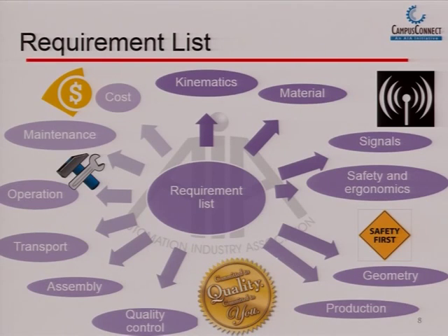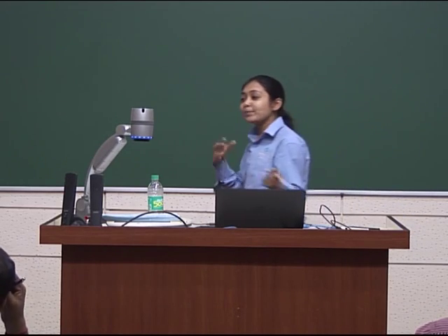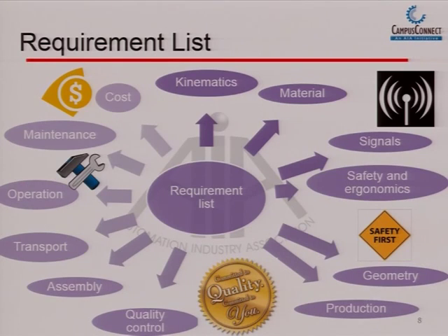And then you have assembly. So we have a different session altogether, which I'm not taking today, on machine design for assembly. So design for assembly is also a new thing. You have to design your machine in such a way that assembly is easier down the line. Because at the end of the day, every machine is not a concept on paper. It has to come down to your shop floor. It has to be designed. It has to be assembled. So everything that you design in your machine, all the things that you think of, should be easily manufacturable, and it should be easily used for assembly.